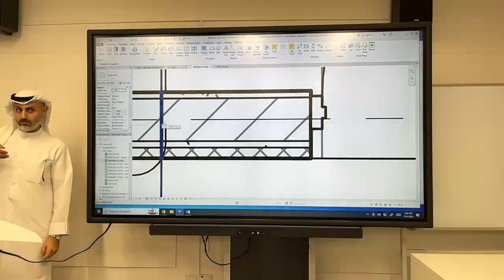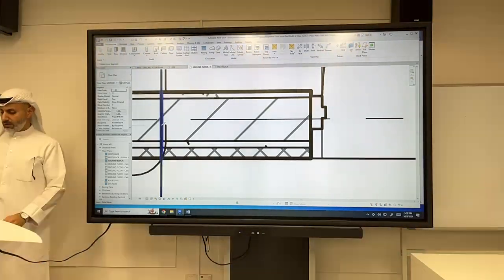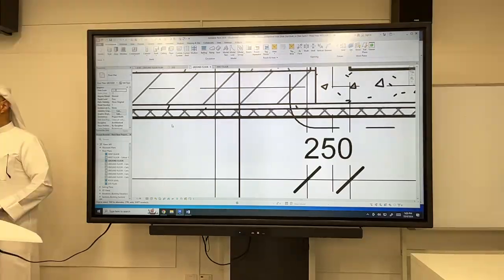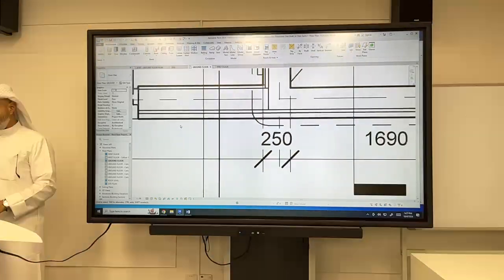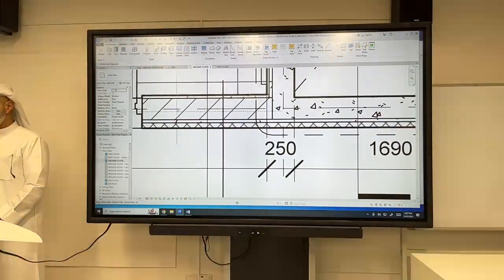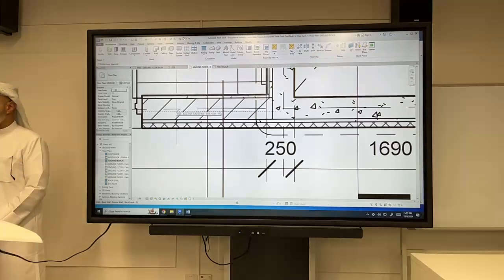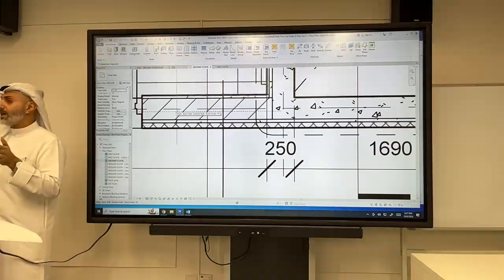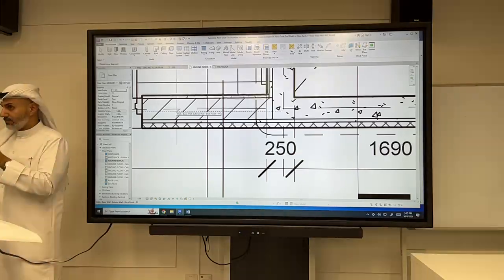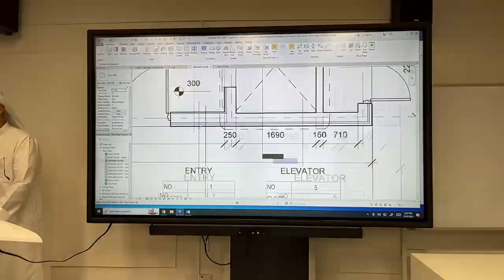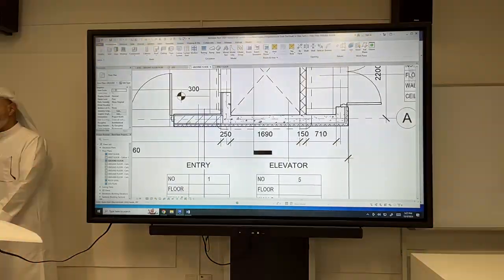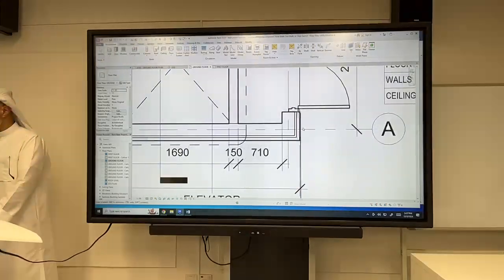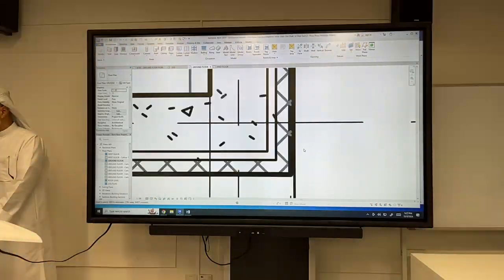It's clear? I now want to cut the wall at a place I want to determine. If I just press SL and cut, it could be a random place. I want a specific place, a round number, every 50 or 100 millimeters. I don't want to leave fractions. Okay? So first I drew, to get to this dimension, the edge of the outer wall.